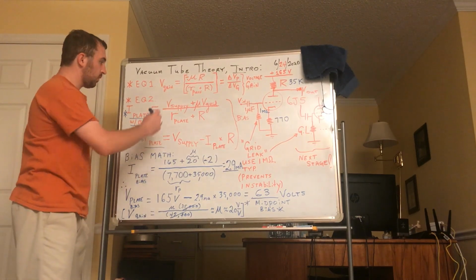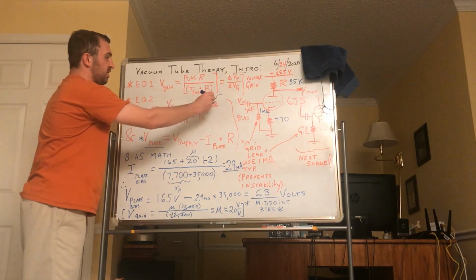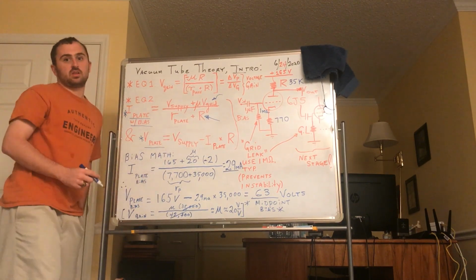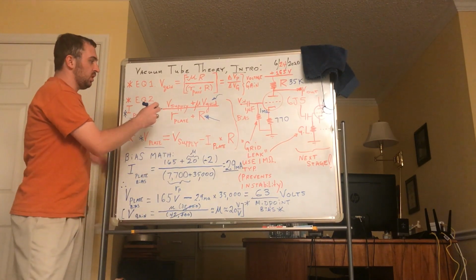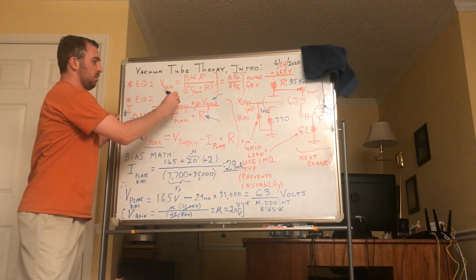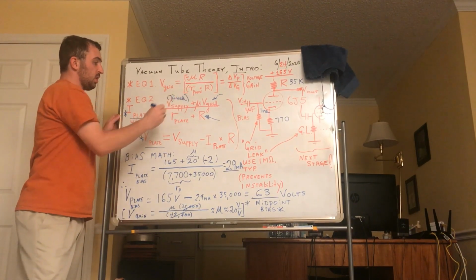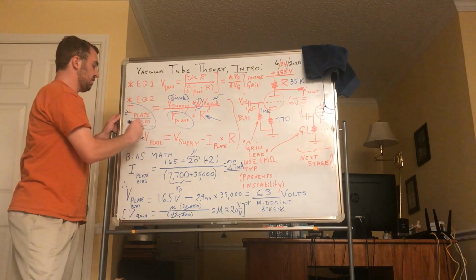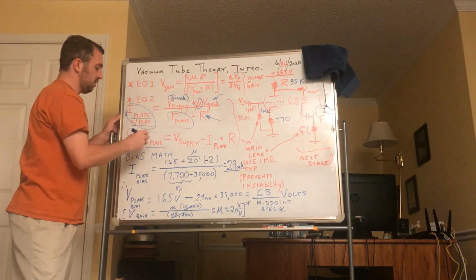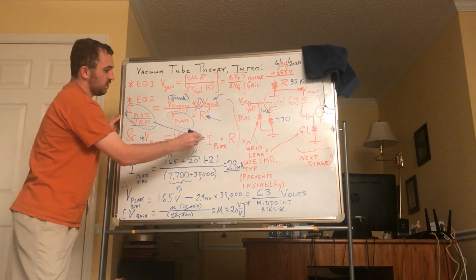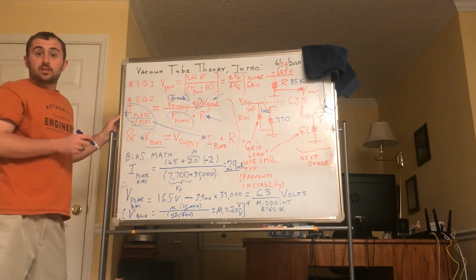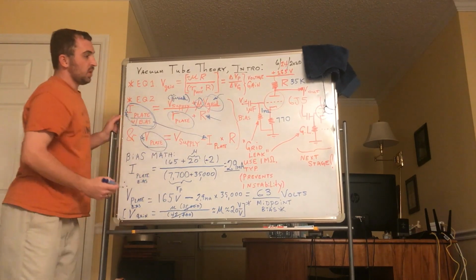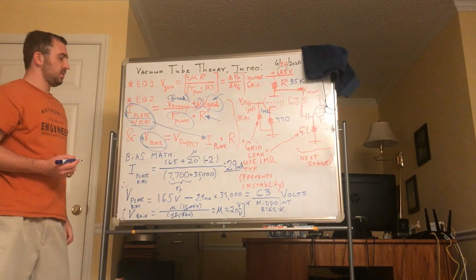So in effect, what we have here is you would set V grid and you would choose a value of R based on signal input and impedance considerations, and then from that point, the supply voltage would be fixed probably. You would choose a tube with a desired mu and R plate, and you would set your desired bias current by fiddling with these factors, and then you would plug this from this equation into this equation right here. And in so doing, you would set the plate voltage and the plate current and the grid voltage, and you would have your bias scheme.